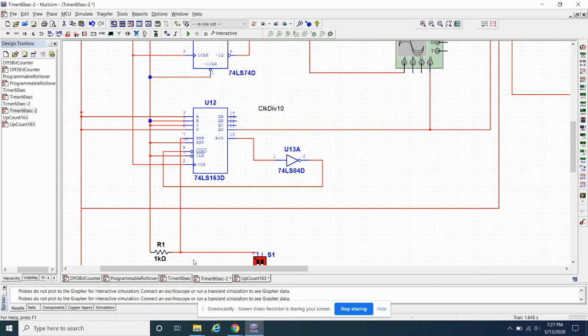Okay, well, to pause the timer, you can use the ENP control bit on this master divider counter that we have, right? So if I'm running this thing with just this master clock and I'm generating this divide by 10 through this circuitry here, I can stop it by simply making this ENP a 0, right?